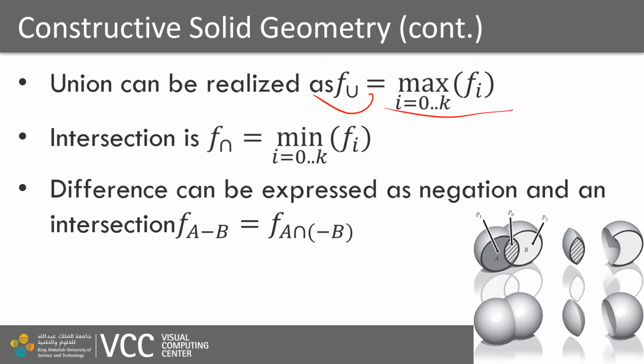So we are here talking about the compositing function, the one which was previously used as a summation. We can replace it with max function, for example, and then this will be a union of all the implicit objects in the scene. For intersection, we can have the min function. Let's have a look how this works.